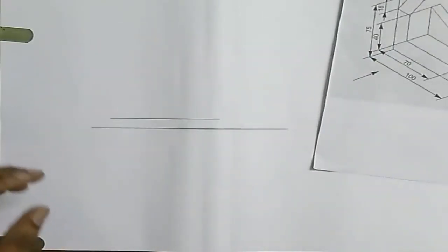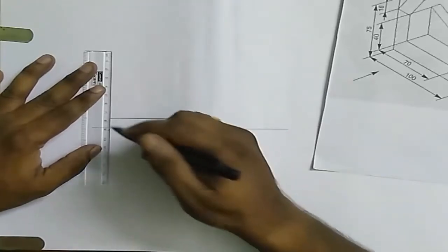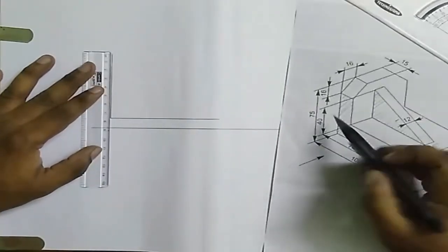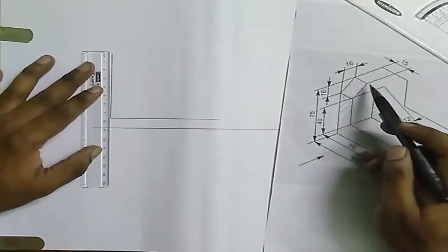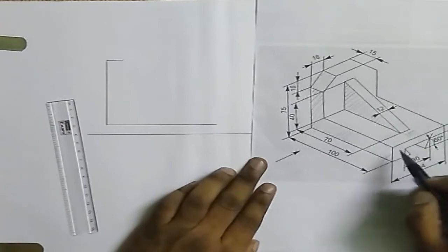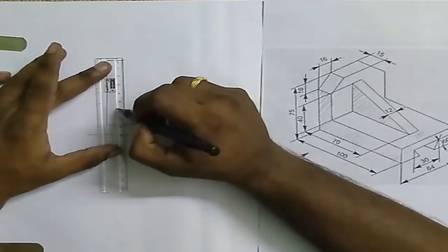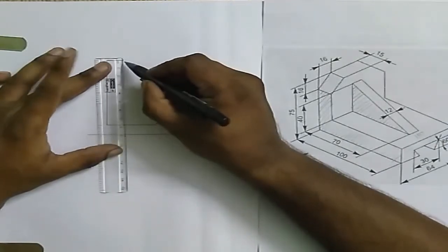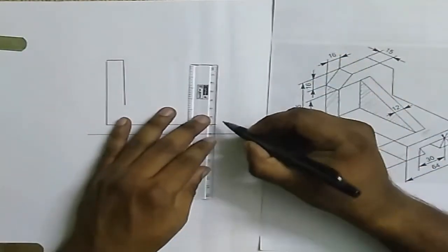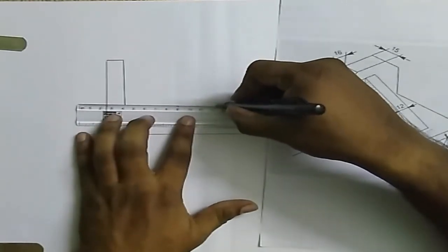Let me take a small scale so that it will be easy. You can try it with the drafter or with other scales also. Roughly it should be perpendicular. So this is my 75 mm line, which has been drawn. Then the thickness is 15 mm. Then this height is 22 mm, so from here 22 mm like this. The total height is 75 mm, so 75 minus 22 will be 53. From here draw a line for 53 mm. Then close the diagram: from here just draw 22 mm height and close this line.